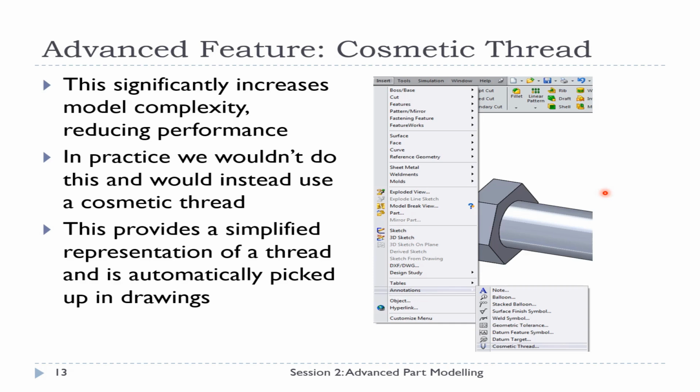So to do that, we can simplify the thread representation using a feature or annotation in SolidWorks called cosmetic thread.